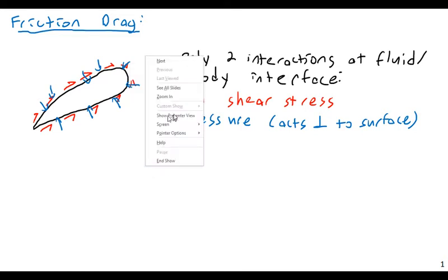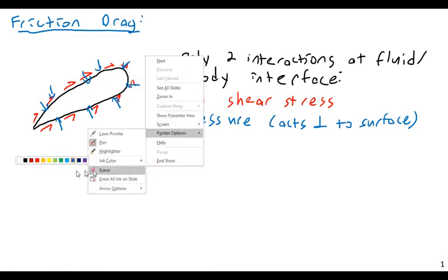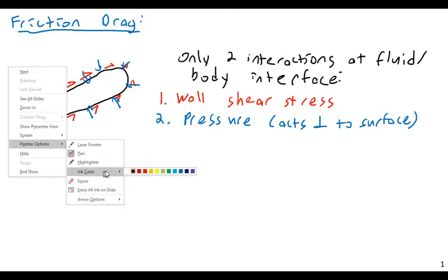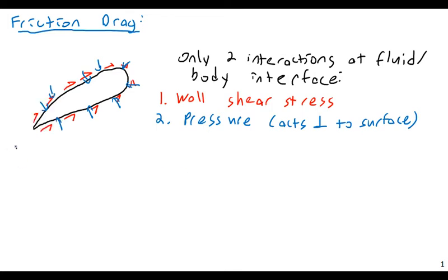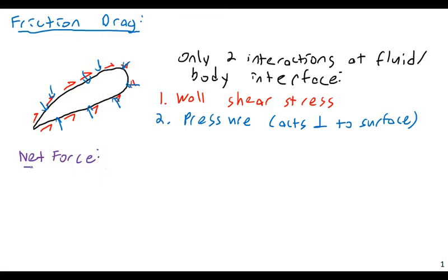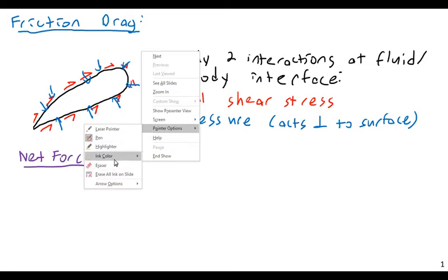And the sum of these, the integral sum of each of these, add up to two things. These sum up to a net force, and for an aerofoil or a body moving through air or any other fluid really, we say that these combine together into two different forces. We'll classify the net force according to the direction of the resultant.